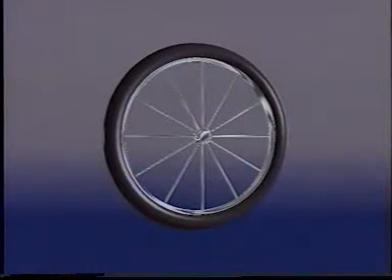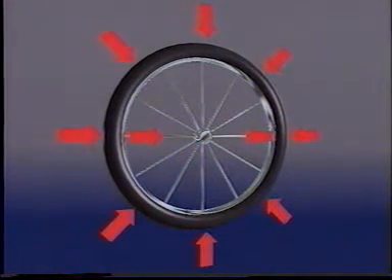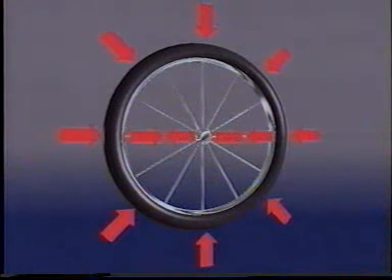Since residual stresses and their directions are so important in failure analysis, let's look at several other assemblies of parts and how they can be considered to have residual stresses. A bicycle wheel is a very light, strong, and carefully designed structure. The wire spokes, assumed here to be radial, are stressed in tension, pulling the rim inward toward compression. At the same time, the spokes pull the tubular hub outward in tension. The significant stresses in this system are in the circumferential and radial directions. The longitudinal or axial stress is negligible and can be ignored.